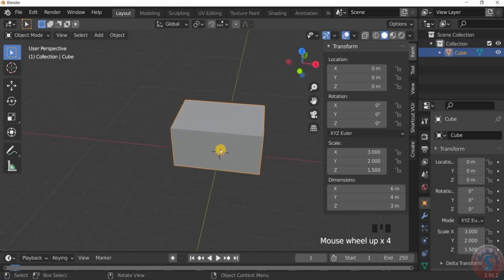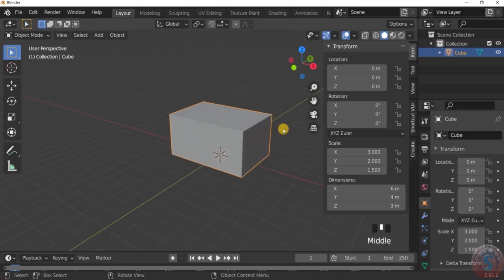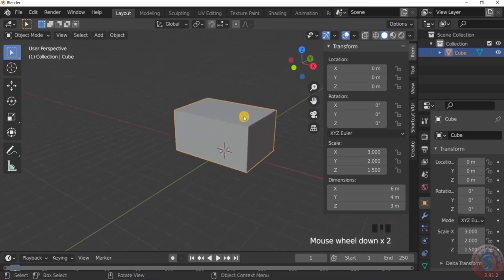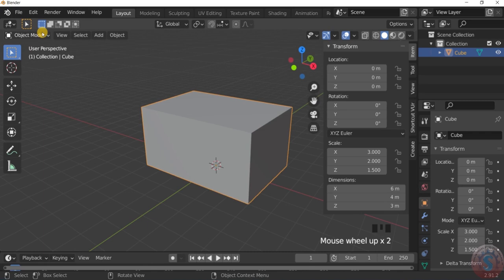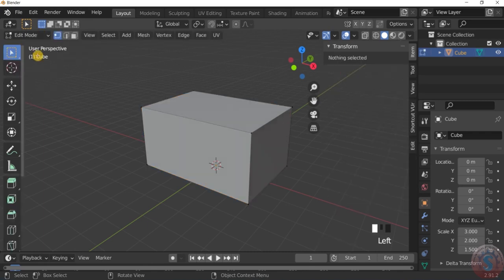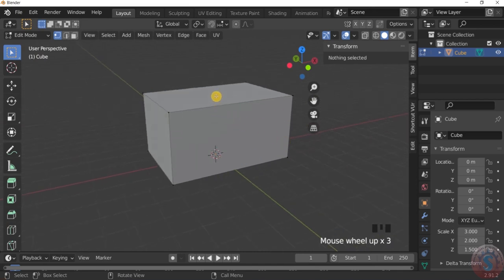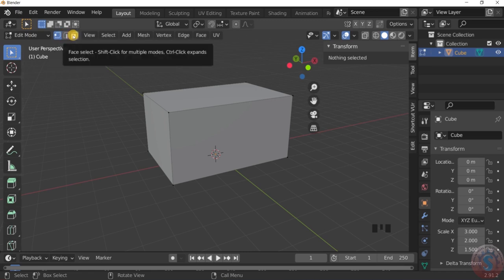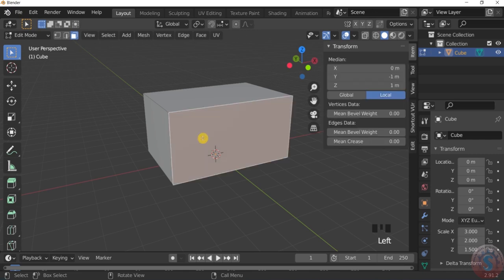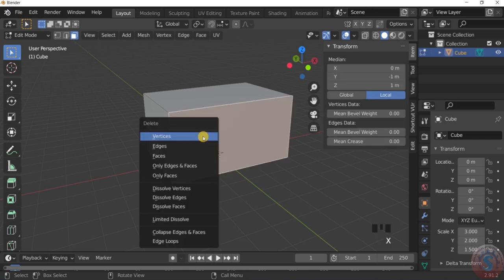Next, you want to develop the windows. Next, this is the one cube, and I want to go from object mode to edit mode by selecting the cube and going into the edit mode here. After selecting the edit mode, here you can observe the vertex and the edge and the face. Select the face option and select this face and click on the X key or delete key.